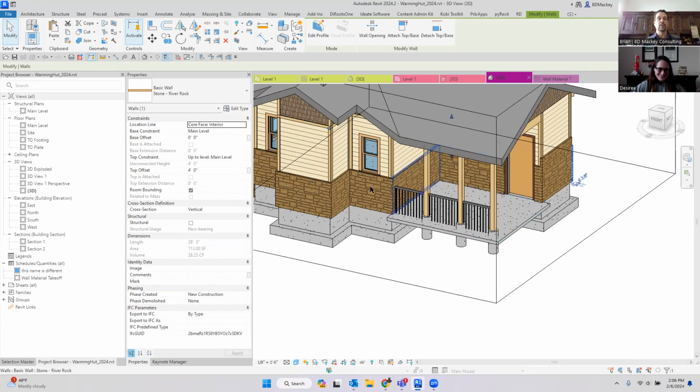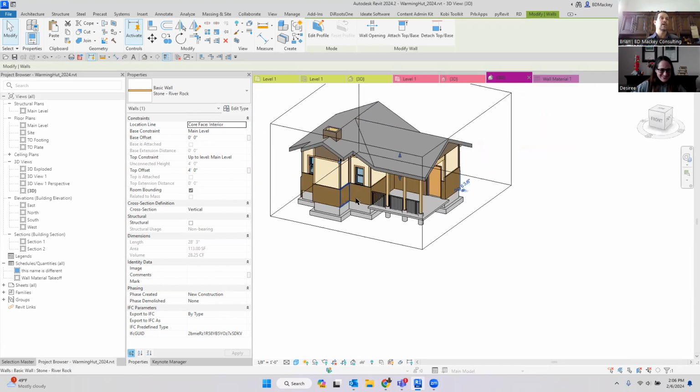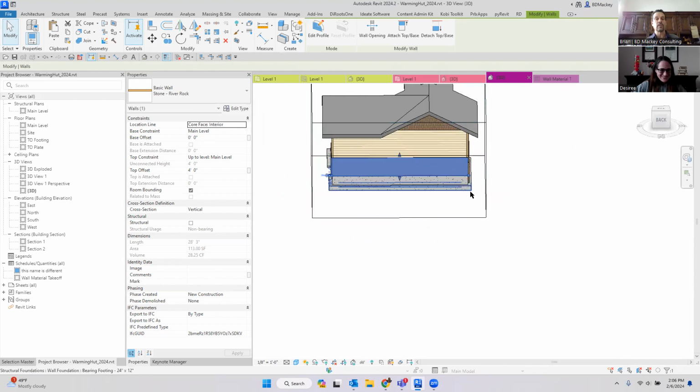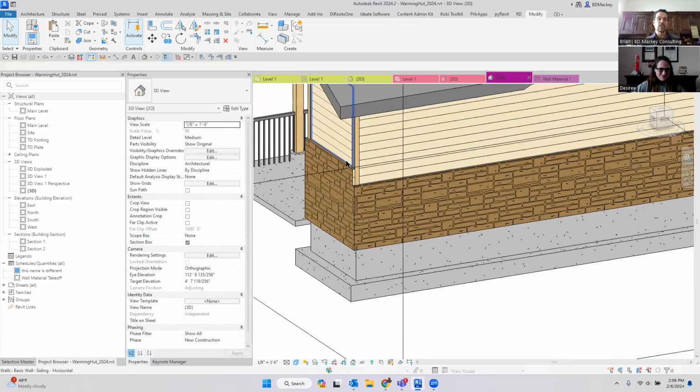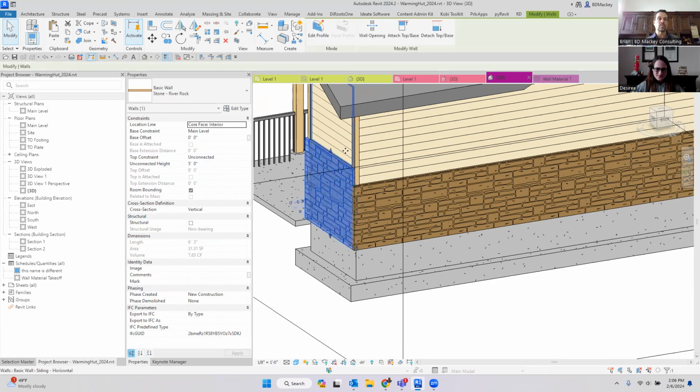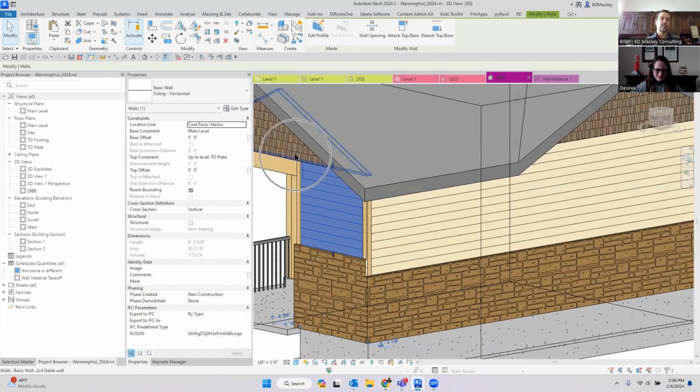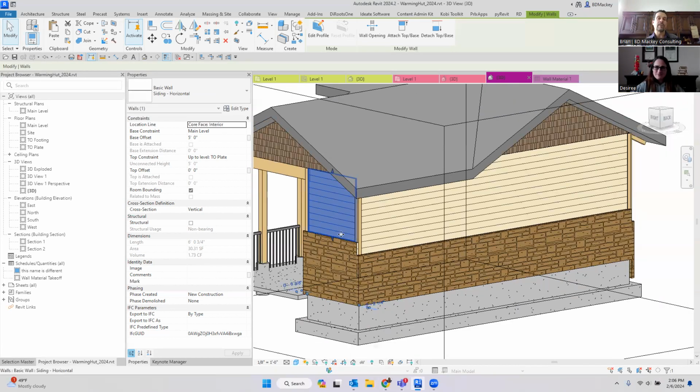Yes, this building, when it was all said and done, ended up being the same height, but not going to do that there. The other problem is if your stacked walls are different thicknesses. So this bottom wall is 2 inches thick, this one's an inch and a half thick, and this one up here is 3/4 of an inch thick, or whatever. When you do that, Revit looks to the base wall's thickness property when doing joins and other things. So if you were to come through here and do that, it's going to be like, oh, my overall thickness is 3 inches. So it's going to kind of ignore what is going on here.